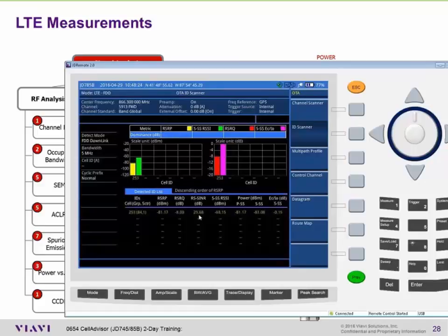But I look at two columns. I look at the SINR. Notice these high 29, 32s. This is a very good SINR value. The full scale, and what I expect to see through a hardwired connection, is actually 40. But high 20s, low 30s, over the air, this is actually considered pretty good. Notice the far right part of this table. This is that dominance, or otherwise the height of that secondary sync, and whether or not there are any other sectors being seen or competing with that secondary sync. In this case, it's very good coverage.